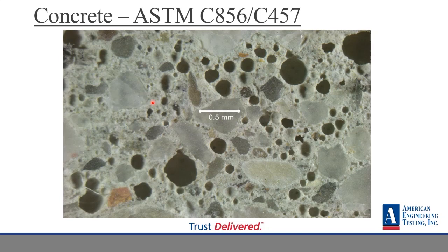I have seen millerite because they were using some of their waste product from a nickel mine as concrete aggregate, again because of location and proximity, and they wanted to reuse that material. So we did see millerite. That was pretty neat, but that doesn't happen too often. Mostly it's just pyrite and some of the normal gangue minerals, I suppose you would call them in the ore world.